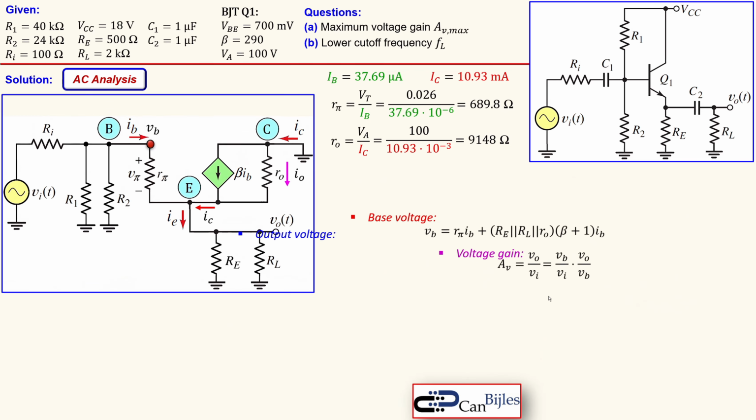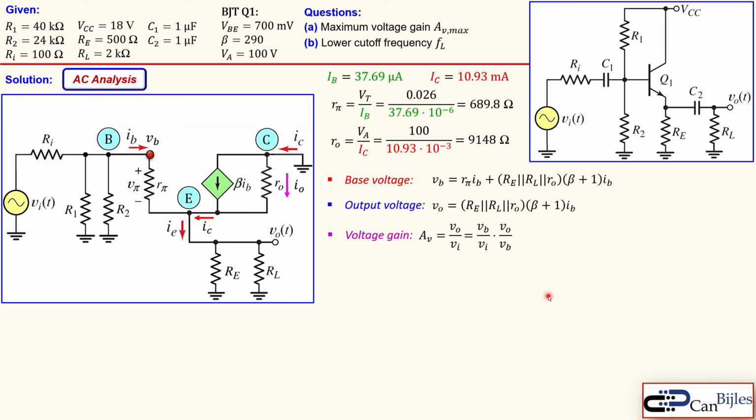Okay, let's bring everything together here and then step by step determine these parts. So I said VO over VB, that's here. So we have now the expression. This is just a voltage divider, effectively. And here I need to look at the base, which I call ZIB, which is the impedance looking at the base node.